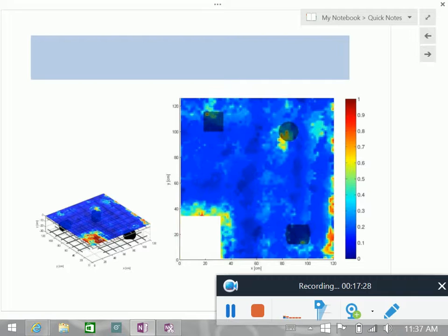Questions? Discussions? So you're saying that impact echo can be used, but it's not a perfect method. It's really good for delamination detection. Really, really good. It's a very cheap method, so people really like it. Any kind of fracture, if you have a plane of fracture, impact echo is great. If you do it at different locations, it's very easy to use.